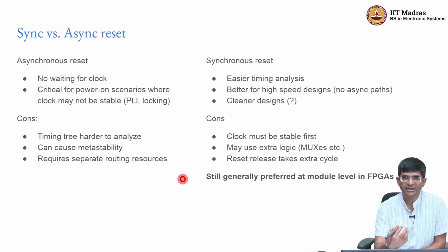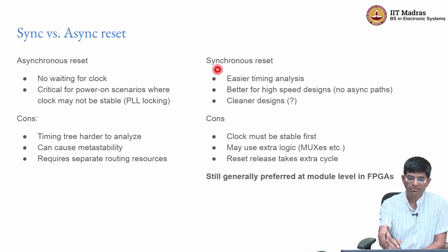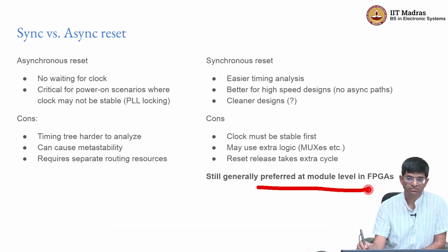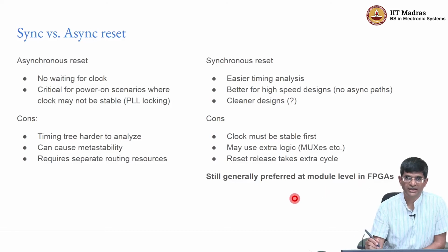You need to wait until the reset has activated, and then one clock cycle has to pass, and only then you take it out of reset. Now, is that going to be a problem? In most cases, not necessarily, but it is a consideration, right? So having said all of that, because of these benefits, especially at the module level, where you are not necessarily dealing with the outside world directly, it is always preferred in terms of FPGA designs especially.